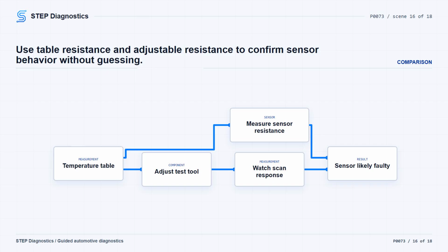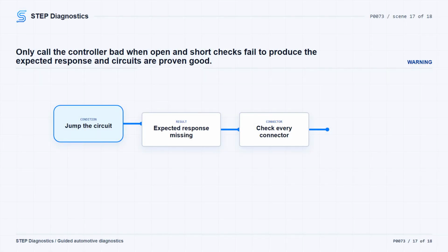25 degrees C/77 degrees F/9720 ohms; 30 degrees C/86 degrees F/7780 ohms; 35 degrees C/95 degrees F/6370 ohms; 40 degrees C/104 degrees F/5200 ohms; and 150 degrees C/302 degrees F/181 ohms, highest possible temperature reading.